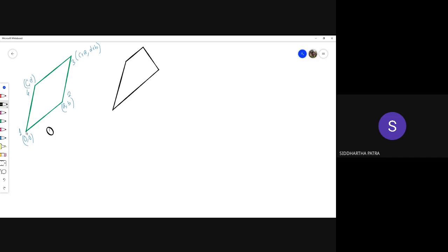Now, if it does represent an area, why is it not a constant? The reason it is not a constant: the Jacobian is supposed to represent not the area, but let's say in the natural coordinate you take a differential area dA natural, and you take the same area element in the physical coordinate dA.